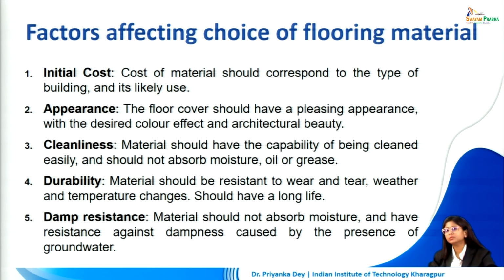The appearance is also another very important factor because the flooring will have a huge impact on the interior design of the space, the overall color scheme, and the look that we are going for in the interior space. Several other aspects with respect to aesthetics would be influenced by the flooring. Now the floor cover should have a pleasing appearance, no doubt. It should give the desired color effect and also maintain the architectural beauty. So that also is a prime factor in selecting the flooring material.